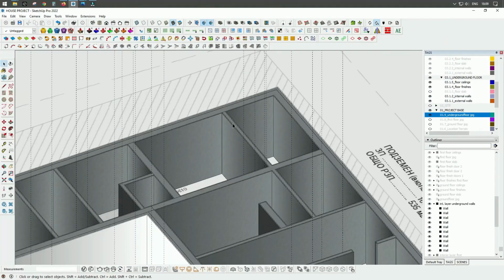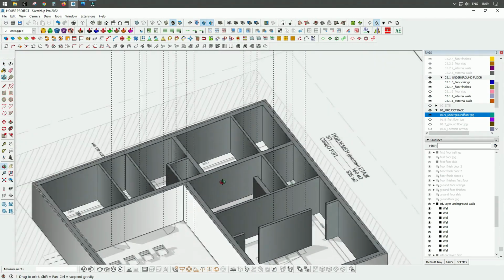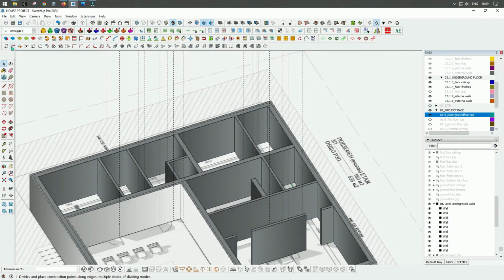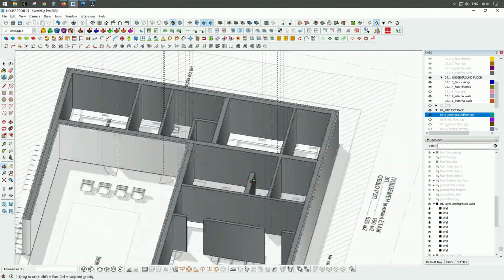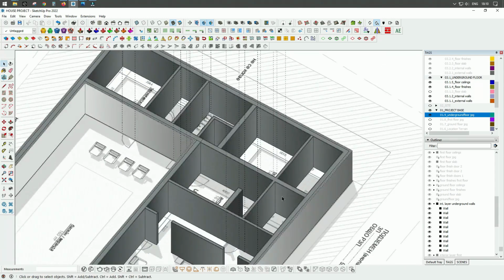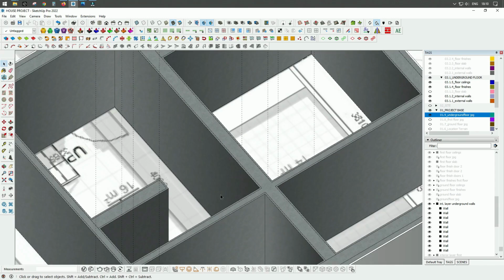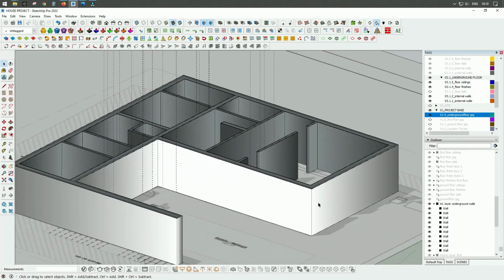So we have all the reference lines and guides, and now I'm going to use the 1001bit toolbar and our tool for openings to create all the openings for interior doors, and later on we will create all the openings concerning our windows.